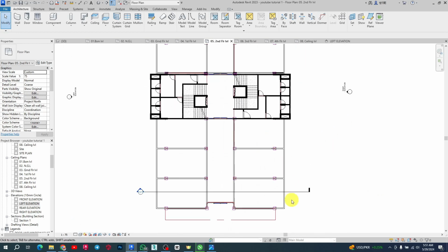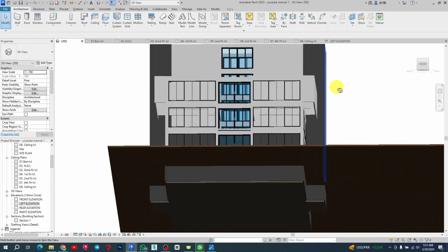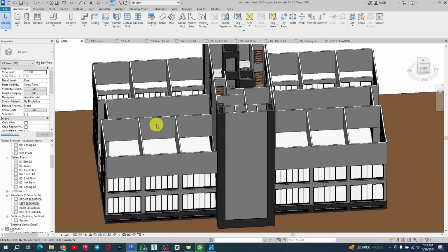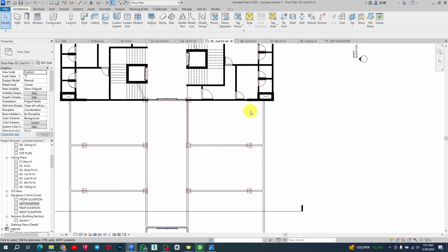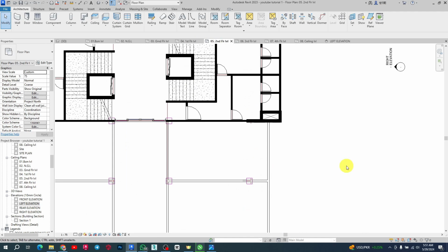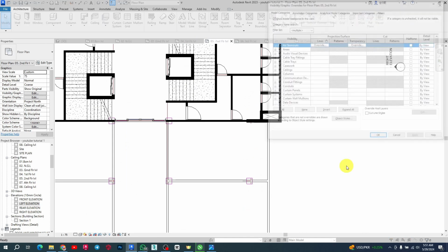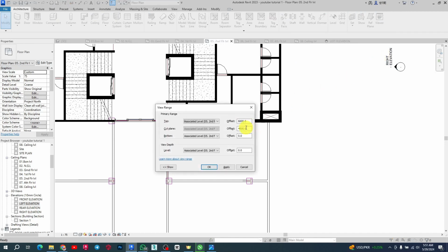second floor, but there's something that is appearing that probably you can notice, right? You notice that the wall itself is not showing that thick line, but this one is showing a few pattern. That is because of the view range, right? So just type VR, that is view range, right? If you see it's at 4,000, that is already above our floor height.